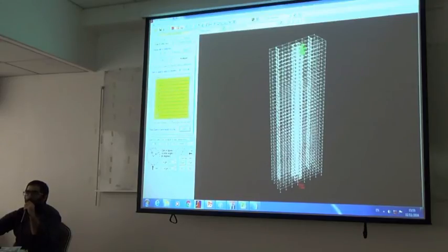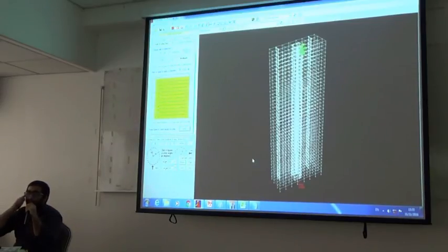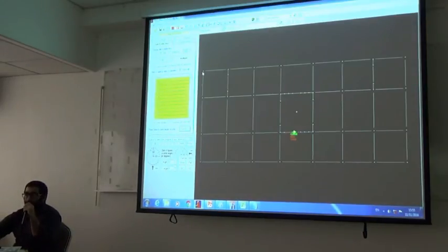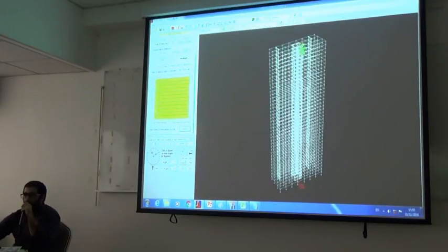The loops that you will see may not be very smooth because the force is not a controlled force. The ground motion is a random force, we cannot control it, right? So to see the hysteretic plot of the girders, I think this one does not have any view, so I'll not go to the entire structure view, but we can just go to the tab that is next to the tab that is already open. The tab is called Hysteretic Loops. You can select this one.